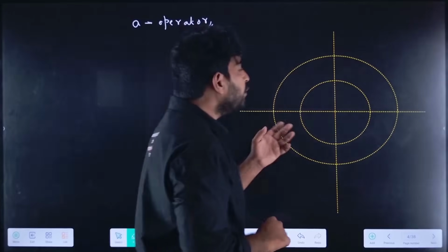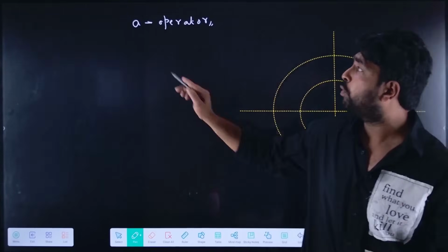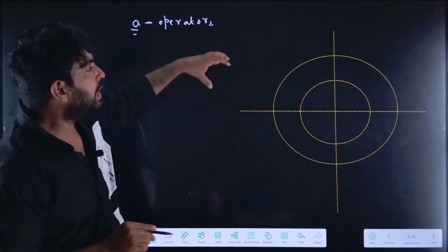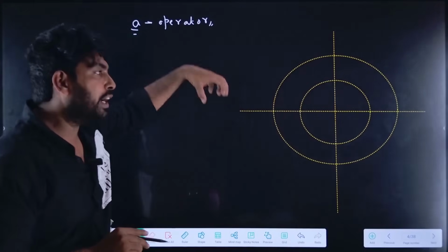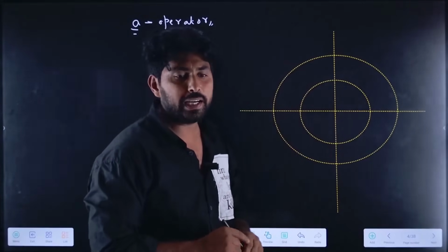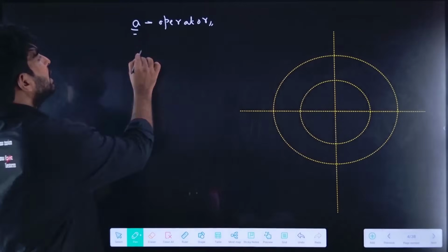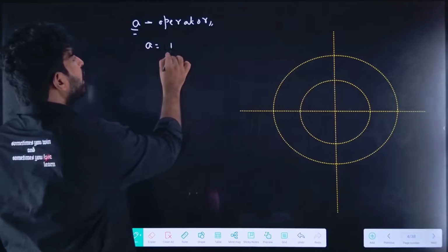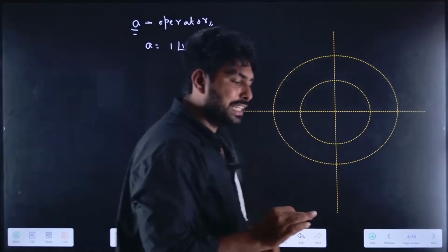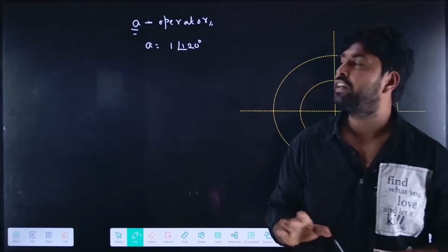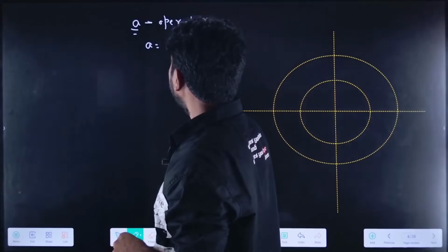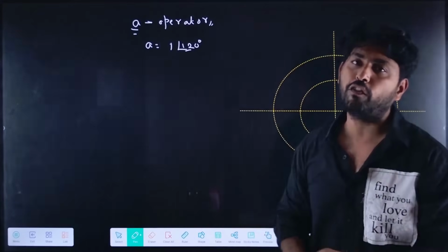In the fault analysis, for example, what is A? Let us see what is A. We should understand this one. If you can find the A value and understand A, you can easily analyze the three phase system. So let me take A equal to 1 at an angle 120. A is equal to 1 at an angle 120 degrees, which is a simple operator. It has a complex value of 1 and the phase displacement will be 120 degrees.